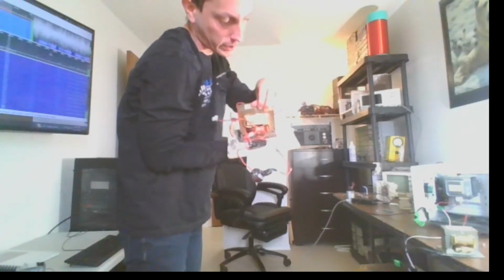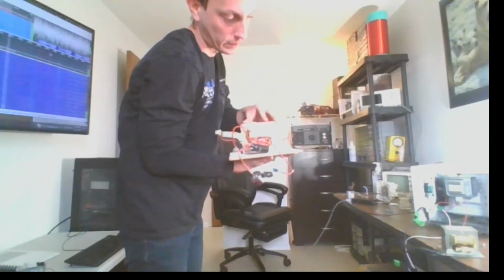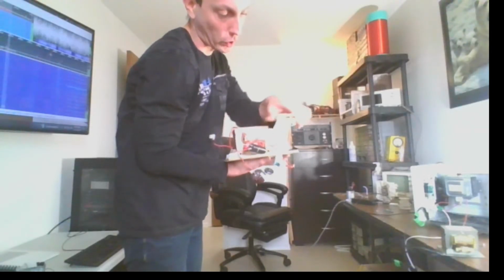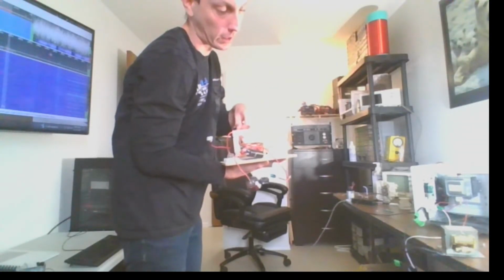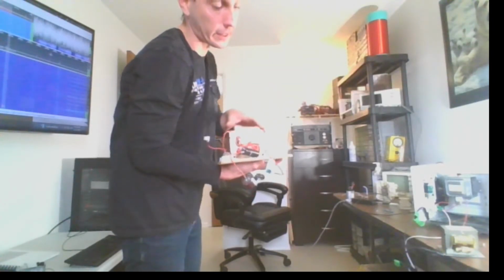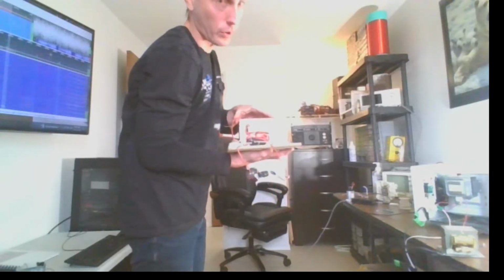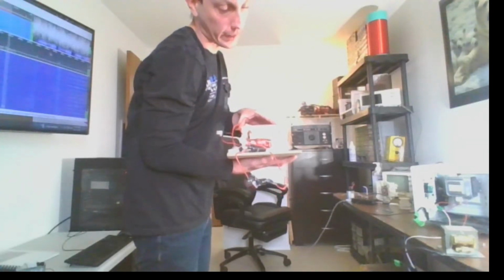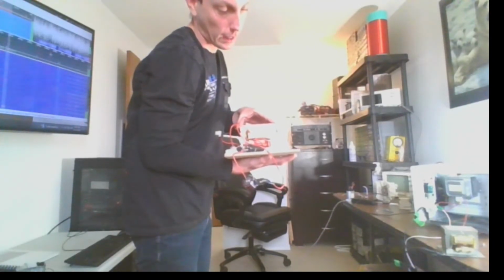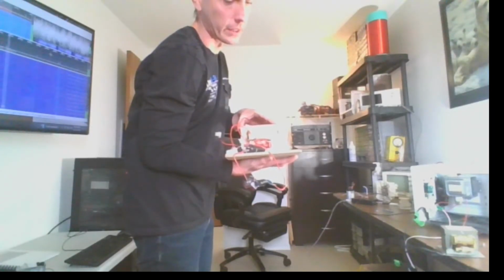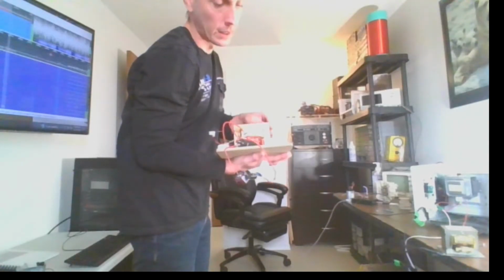But when these capacitors were all charged and I discharged them, you get a big paff, right? Waited 15 seconds, paff again. So at that point I shorted it out for 1 minute, completely shorted out. Took that off, waited maybe half a minute or so, paff again. For about half an hour it kept doing that. So I understand about the memory effect, but I must have left it completely shorted out on a thick cable, where you'd see zero, for over a minute, and even then it was able to bounce back.